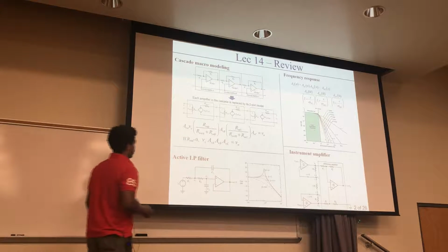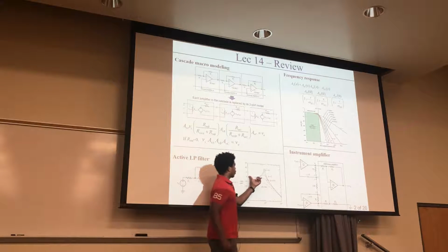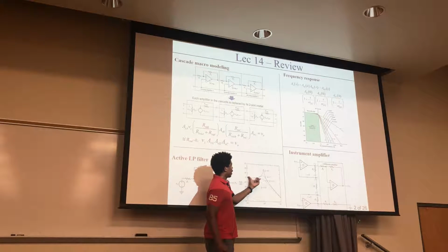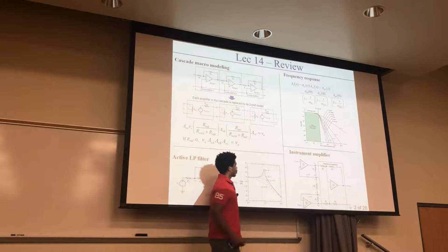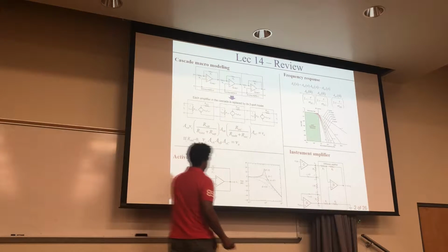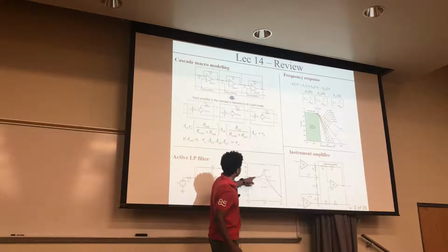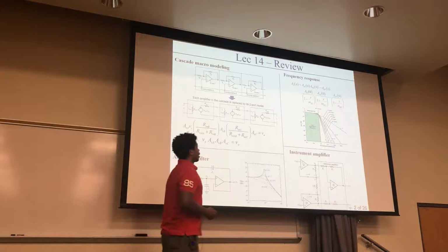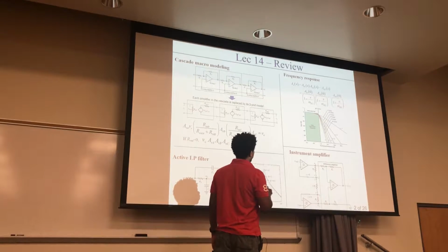We also looked at a low-pass filter, where these frequencies get through. If you have a high Q, it'll peak right here before the cutoff starts going down. But this is the one you typically want, this path. By chaining these together, you get higher and higher orders.